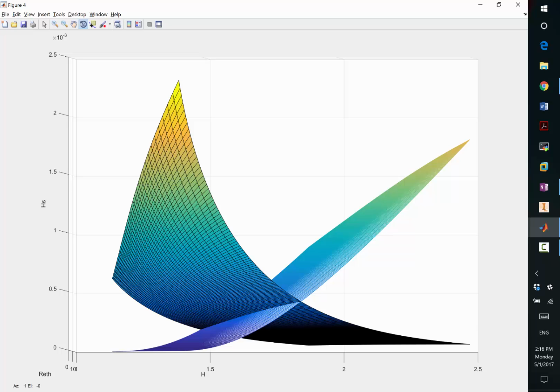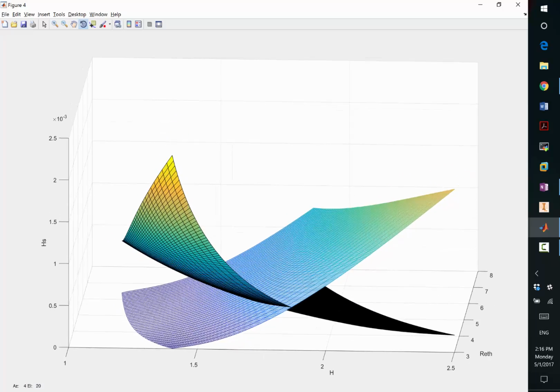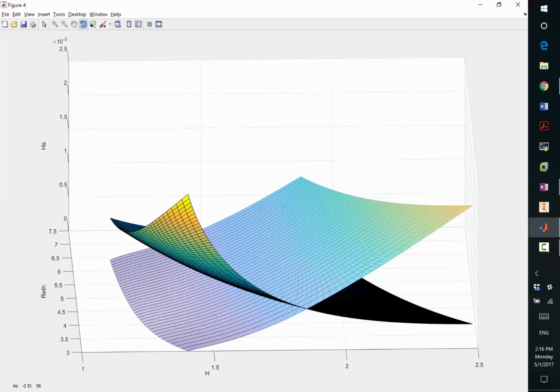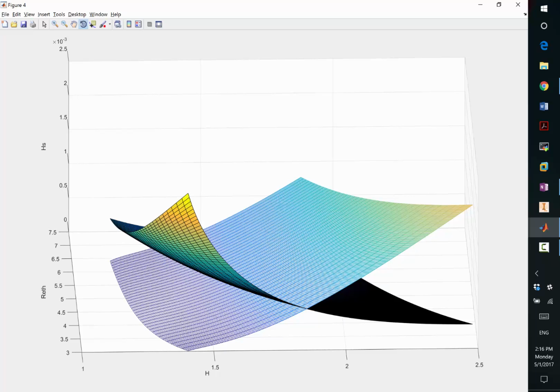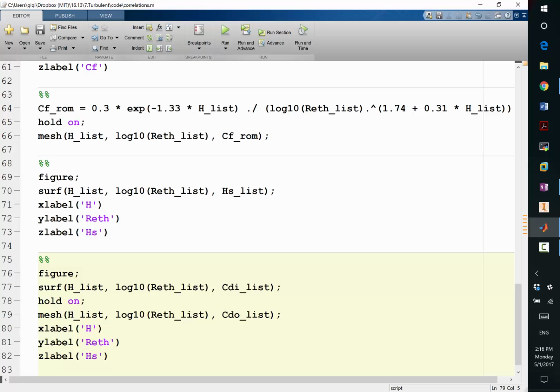All right, and if you look at the total dissipation, when you have a separating or separated turbulent boundary layer, the total dissipation is actually higher. You get a lot of dissipation through the turbulence. All right, so this is how we get the correlations between the different boundary layer thickness and the closure terms we needed to integrate the